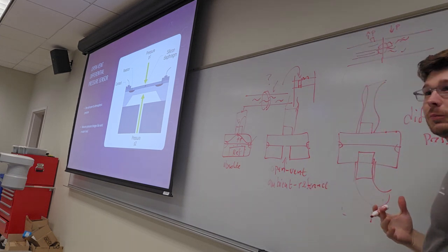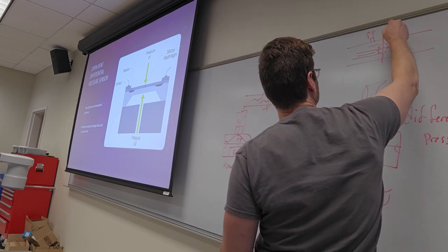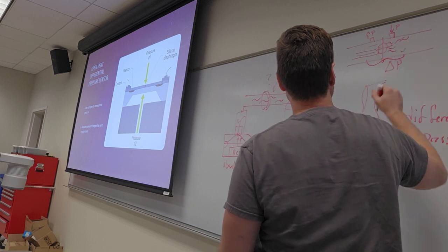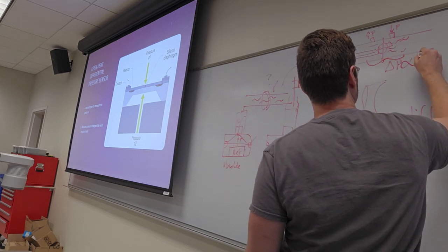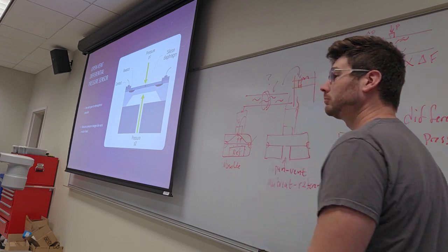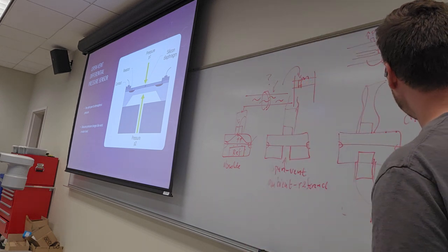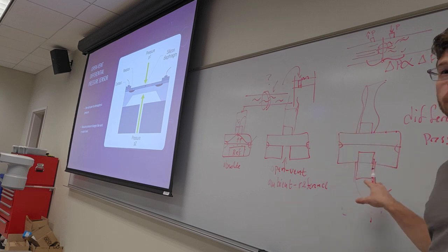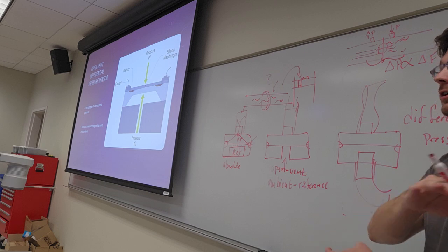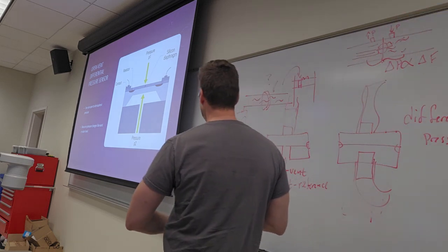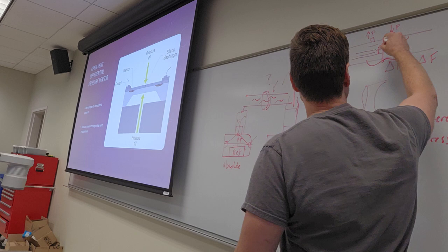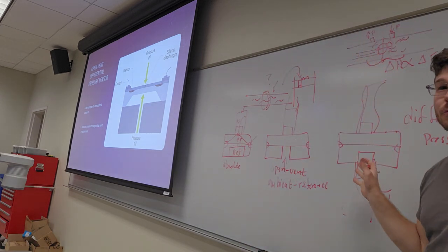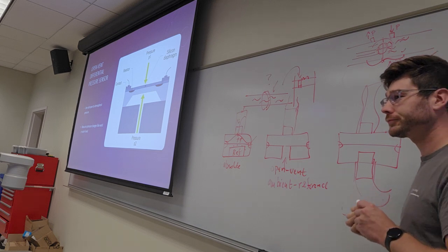But the cool thing is if you monitor the differential, right, the change in pressure from one side of that feature to the other, that change in pressure is equal to the change in flow. So you now have a flow meter using a pressure sensor, right? Entirely just how you hooked it up and how you program the system, you could get an exceptionally accurate and amazing non-contact sensor, right? We don't have a pinwheel in the middle of our sludge getting clogged or whatever, okay? It's one potential solution to the problem.